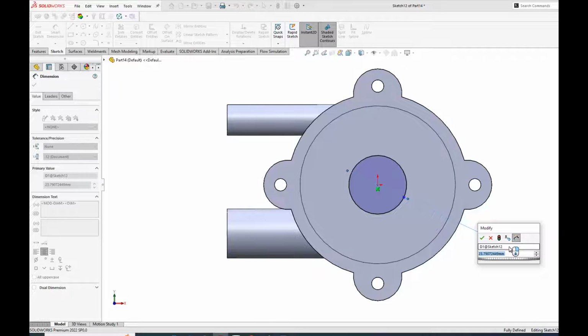So I would say maybe 22.1, 22.2. You know, there's a little gap, but the ball bearing fits kind of tight, right? You don't want the ball bearing dancing on this. So you want a very good fit. For the time being, you can add like 1%, 2%, 5% maximum and see how well it fits. But in the meantime, I'm gonna set it to 22 because that's what the specs say about the ball bearing.